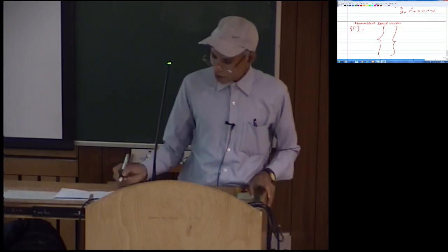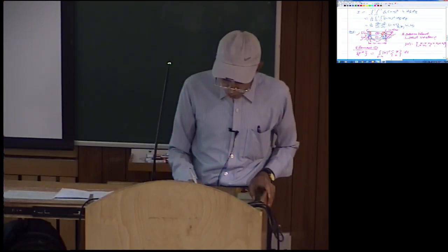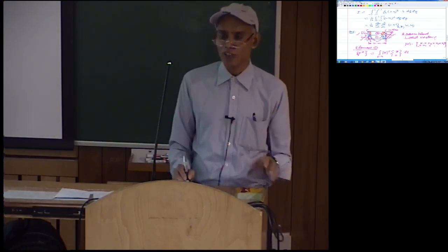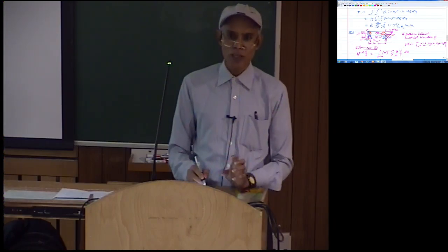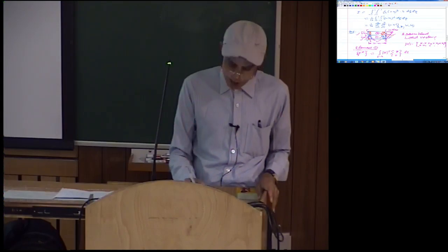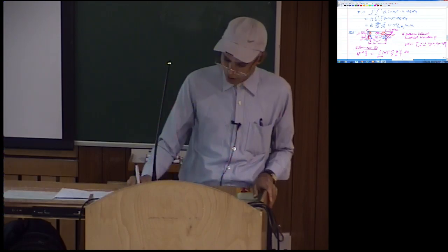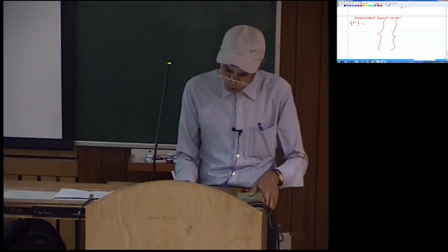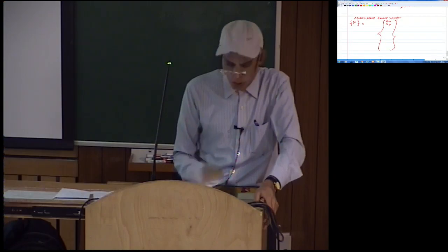So the first global node is the corner node here, and you expect to have 2 reaction forces, because it is constrained to move both, it is not allowed to move along x and y directions. So you will have corresponding reaction forces, which would be actually the integral along this edge of the unknown distributed reaction here. So we can represent that by a concentrated reaction force. So you can maybe say that as F1x and F1y.